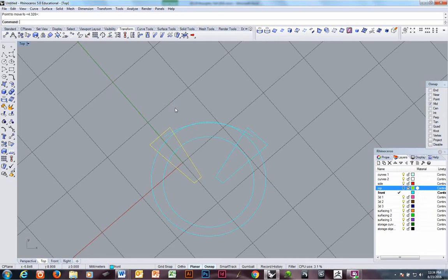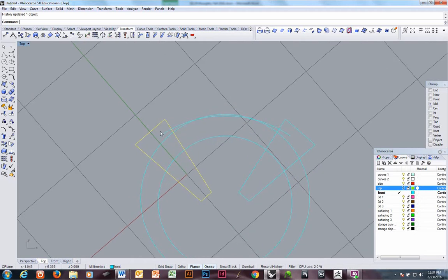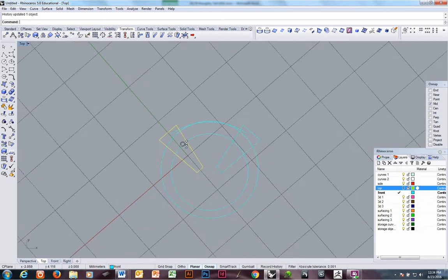Now, actually, I have to be careful. I have to leave enough elevation that I actually have room for my half-rounded flutes there. I have to visualize how much metal I think I need to make 3 loops, 3 flutes. Boom, boom, boom. That's probably more than I need. I want to minimize it because anything I do over here is going to be more exaggerated over here. It just is.